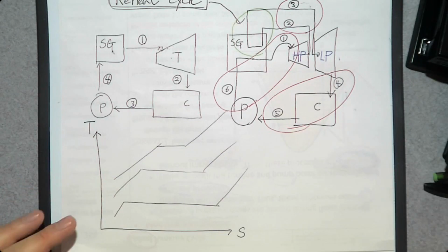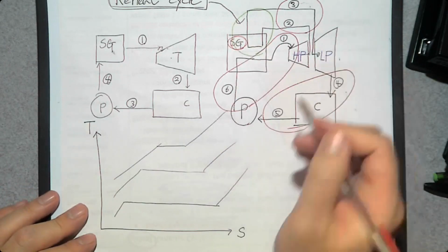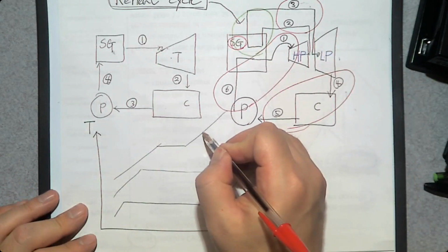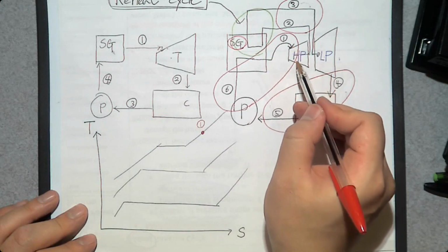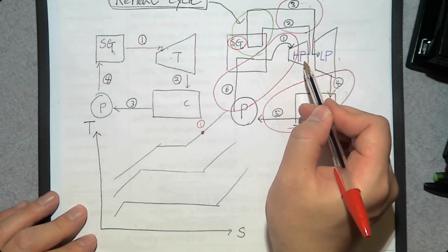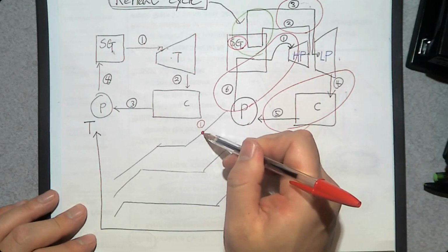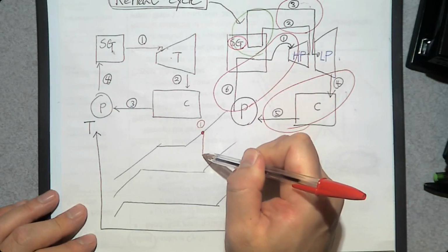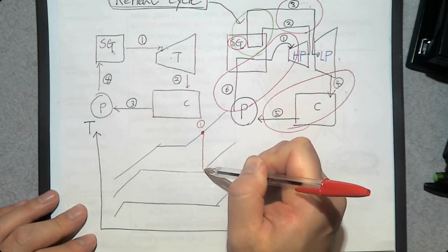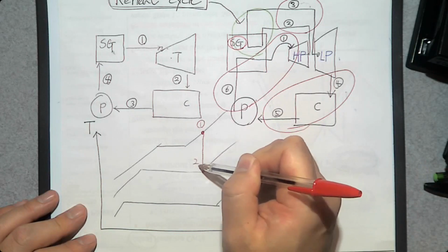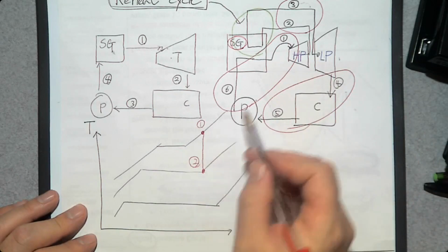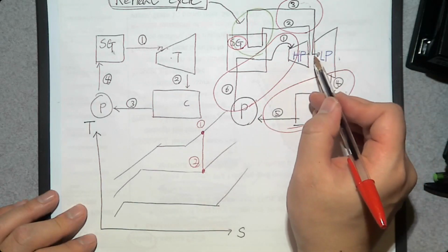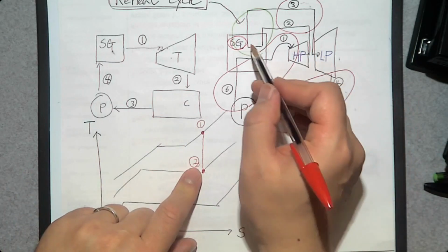So I'm going to say the steam generator produces the superheated vapor. So this is number 1. Now this number 1 goes into this high pressure turbine. So it's going to expand in the high pressure turbine isentropically up to number 2. Then, we already lost too much power to produce the turbine power. Let's return this back to the steam generator.